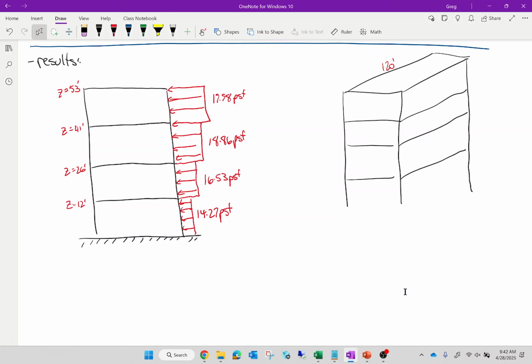Now I want you to ignore the frames and look only at the floor system. So I've got this floor system, maybe a better way of doing it, maybe I'll fix this a little bit, make it a little bit more even. Okay, that's a little better. So this point right here is the center of rigidity of the floor system, or the bracing system. Where's the center of mass of this floor slab? You know, this is an angle. Maybe it's right there.